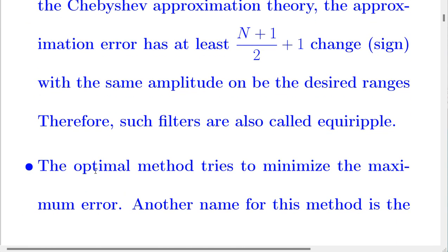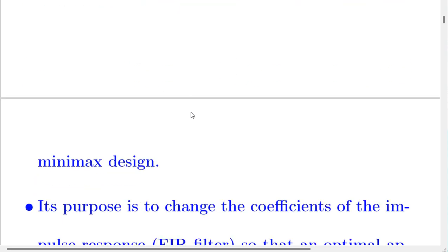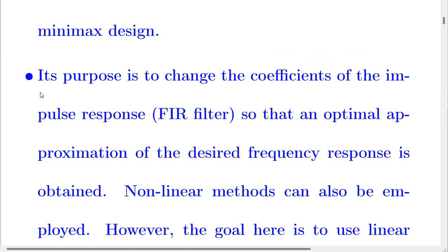Therefore, such filters are also called equi-ripple. The optimal method tries to minimize the maximum error. Another name for this method is the minimax design or minimax criteria.